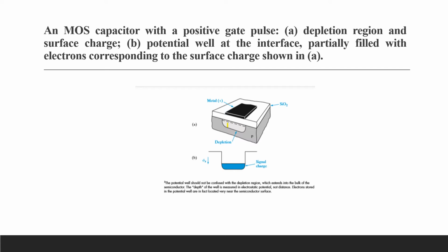If instead of steady state bias, we apply a positive pulse to the MOS gate electrode, a deep potential well is first created. Before inversion has occurred by thermal generation, the depletion width is greater than it would be at equilibrium. This transient condition is sometimes called deep depletion. If we can inject electrons into a potential well, electrically or optically, they will be stored there. The storage is temporary, however, because we must move the electrons out to another storage location before the thermal generation becomes appreciable.